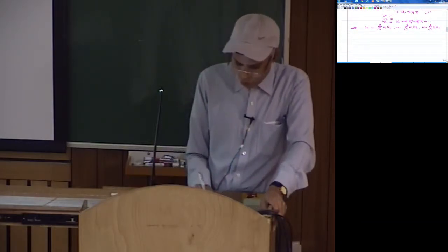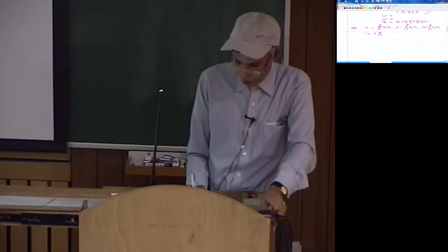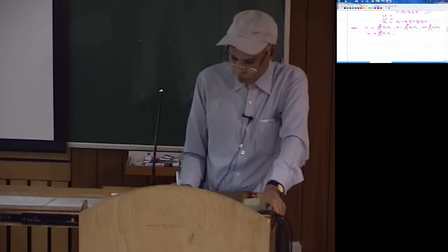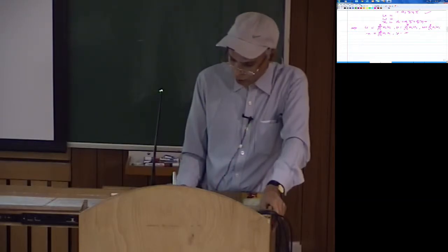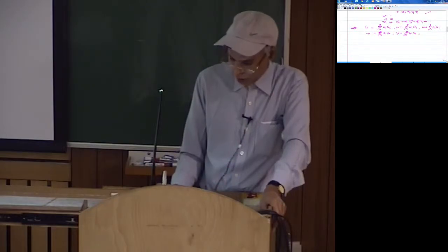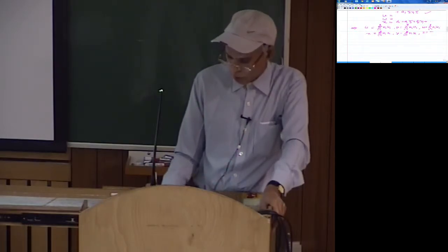So also for x, y and z. You would be able to write x as i going from 1 to 8, Ni xi in isoparametric formulation. Similarly y is going to be the sum from 1 to 8 of Ni yi, and z would be similarly i going from 1 to 8, Ni zi.